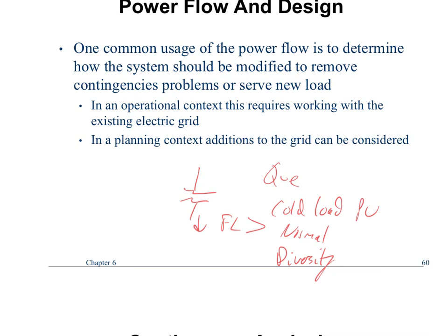So you actually have conditions where your system is under stress because the load is so high. And your cold load pickup is higher than the actual tripping characteristic of what it should be. So the line is stressed out, but it's only going to be stressed out for maybe half an hour to an hour. So when is cold load done? What would it be, the starting currents of all the